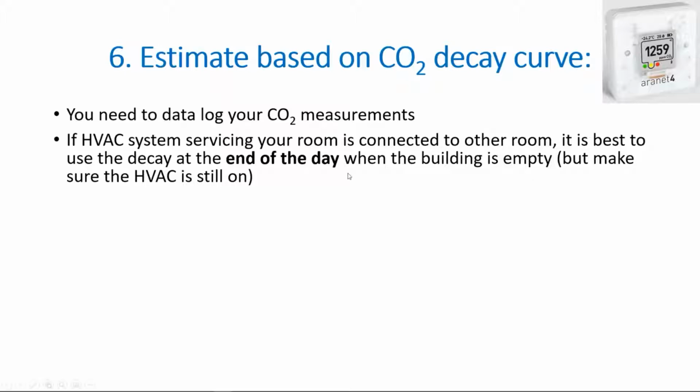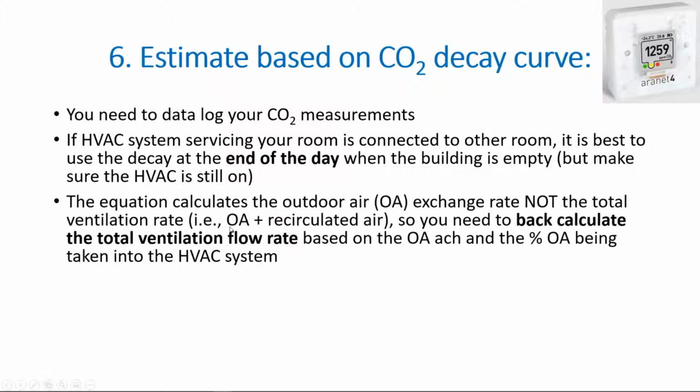But waiting till the end of the day, you have to make sure that the HVAC is still on when the decay happens. So the equation calculates the outdoor air exchange rate, not the total ventilation rate. So you need to back calculate the total ventilation rate based on the percentage of outdoor air.